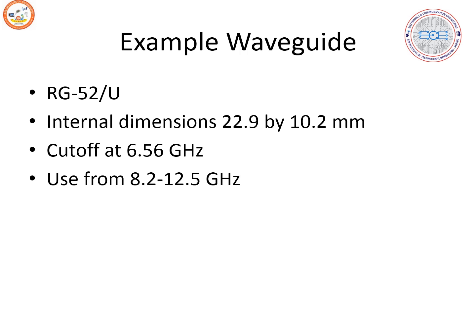So in today's session, we have learnt about coaxial cables, and how to evaluate the characteristic impedance Z0 value, and different types of connectors, N type, TNC type, BNC type, and their frequency ranges. Then we moved to another type of transmission media, the waveguide, and its different types: rectangular, circular, and elliptical. Then we covered the rectangular waveguide, the dominant mode definition, how to identify the mode of propagation in a waveguide, then an example and the cutoff frequency definition.